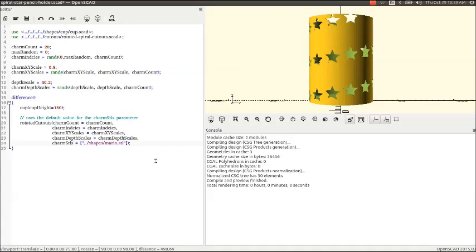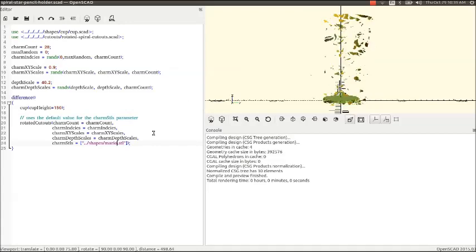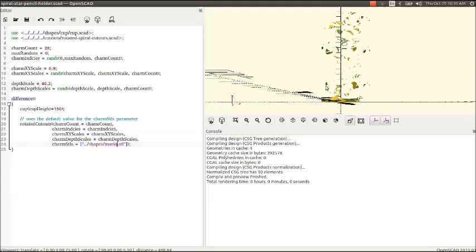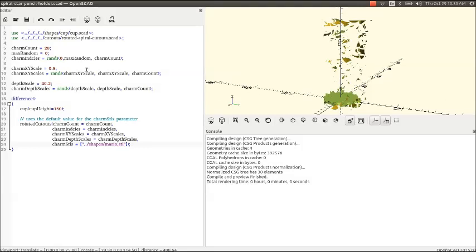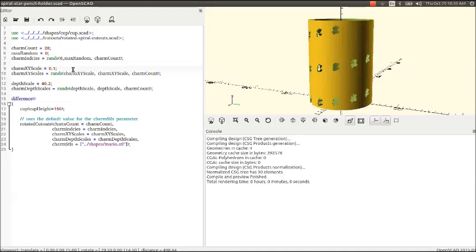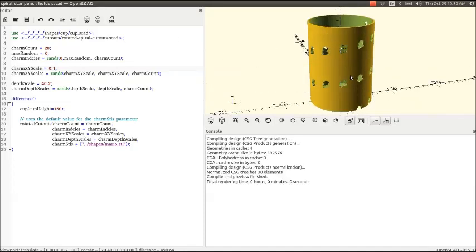And then when you hit Control S, you'll notice that it changed the model, but it's way off from what we want, and that's because we haven't changed the scale yet, which has a current value, like I mentioned, of 0.9. And I've done this a couple of times already, so I know a good scale would be 0.1. Again, Control S will update the model, and now we have Mario jumping all over the pencil holder.